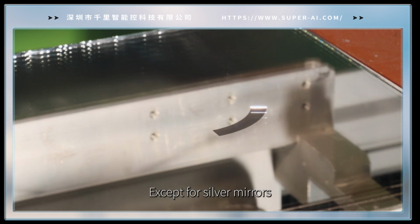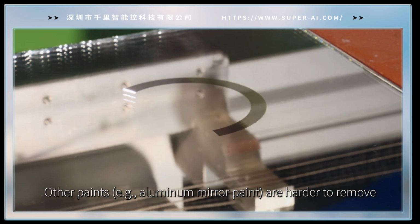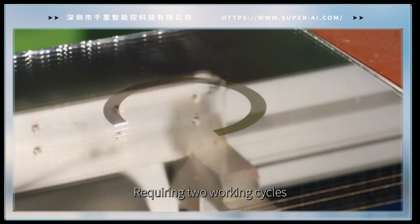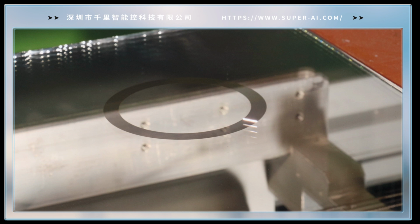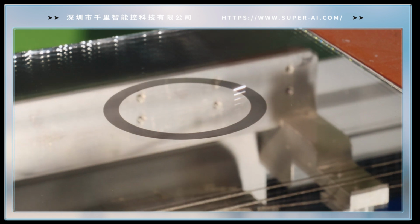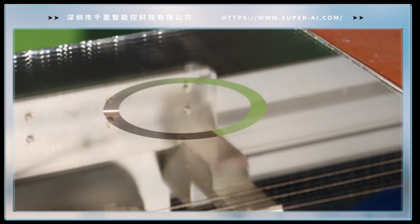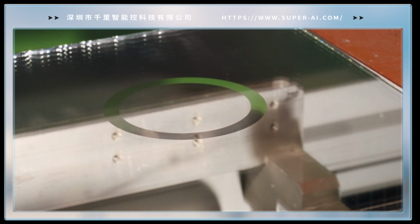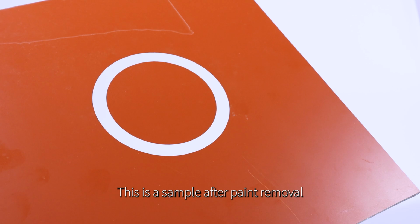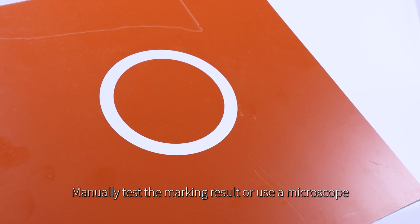Except for silver mirrors, other paints, for example, aluminum mirror paint, are harder to remove, requiring 2 working cycles. Adjust based on actual conditions. This is a sample after paint removal. Manually test the marking result or use a microscope.